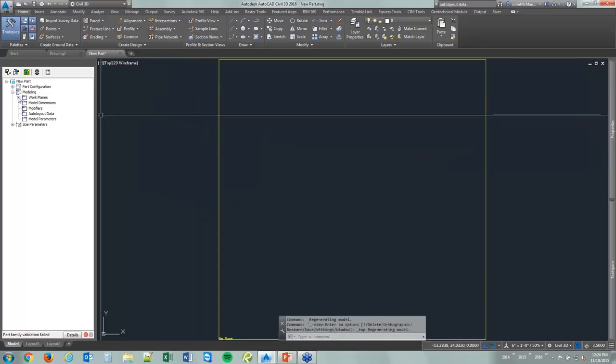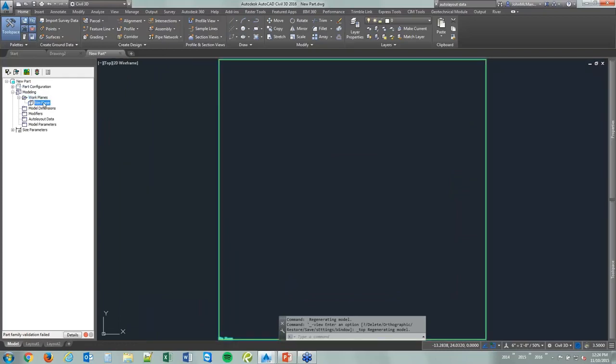Snap back to top here. So under our work plane, we're going to want to add in a profile. A profile, as I hover over this, you could have different types of shapes, and you could have a custom one that you had drawn from other pieces of geometry. I don't necessarily recommend defining it with your own geometry if you can avoid it.